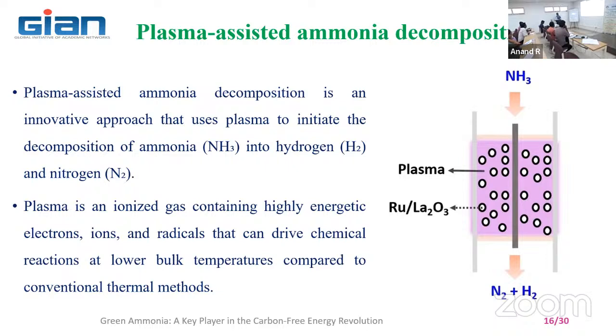That depends on this: for all the thermal modes or electrical heating modes, you are providing heat from the surroundings, like solar radiation reaching your body, through radiation, convection and conduction. Whereas with the microwave, heat is generated inside the body. There is a component called a magnetron. We provide 20 kilowatts, maintaining the frequency, and create the microwave. The microwave is not created outside and sent in like solar radiation; it is created inside.